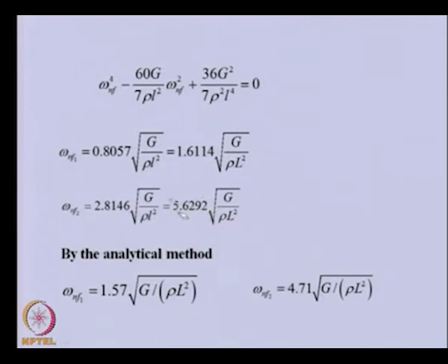So the second natural frequency is not that accurate here, but if we take more number of elements, we expect the finite element method will give better results, closer to the closed form solutions.